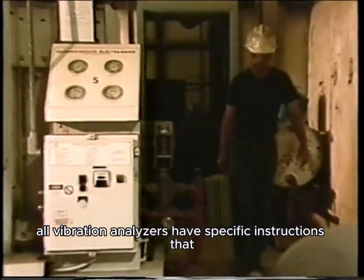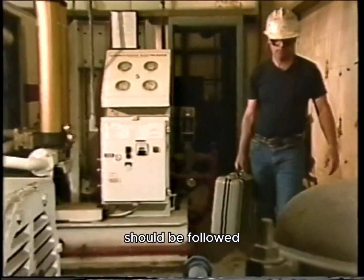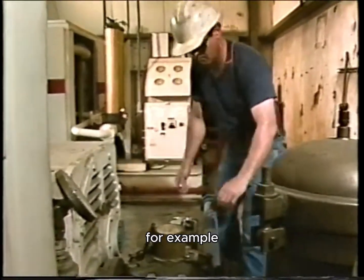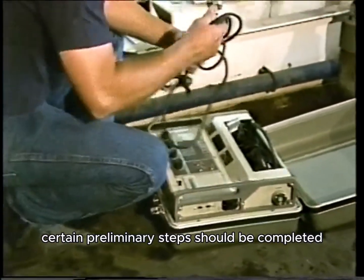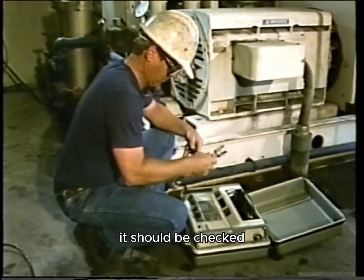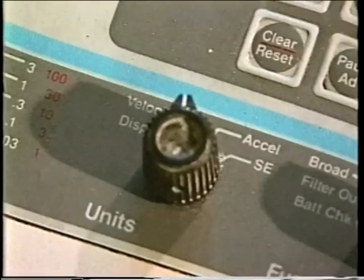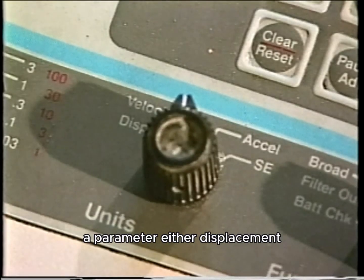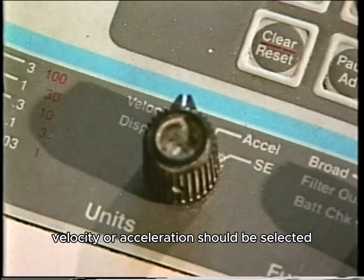All vibration analyzers have specific instructions that should be followed to ensure that the data collected is accurate. For example, certain preliminary steps should be completed before using the unit. First, it should be checked to make sure that it's in good shape. Once the unit has been checked, a parameter, either displacement, velocity, or acceleration, should be selected.